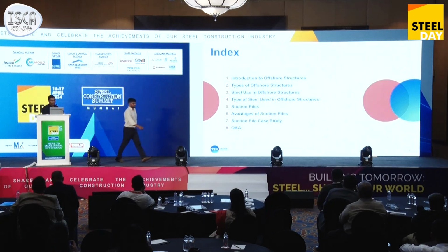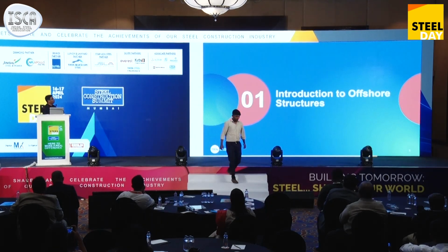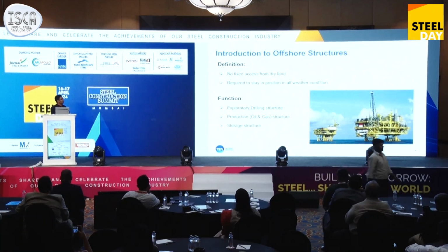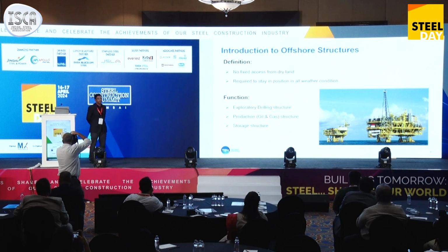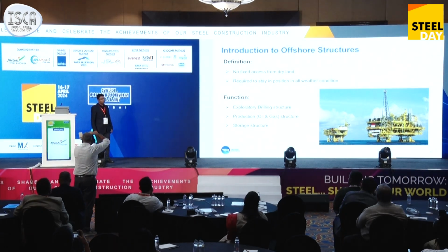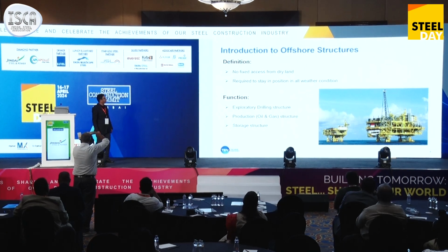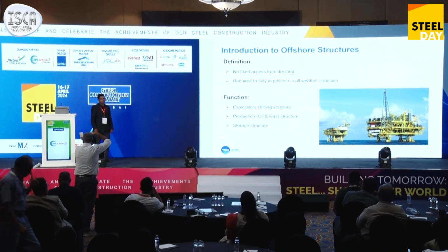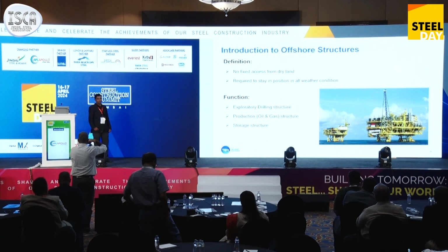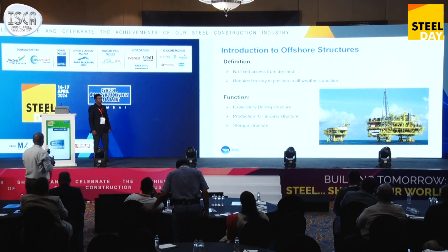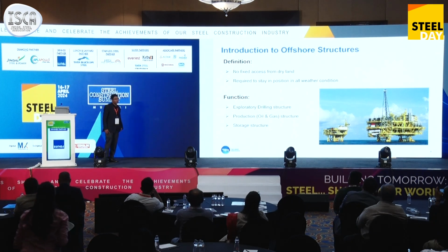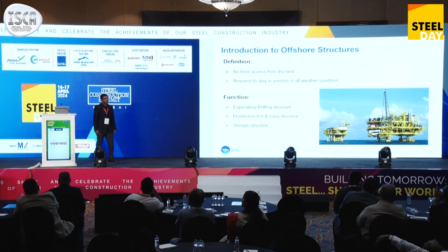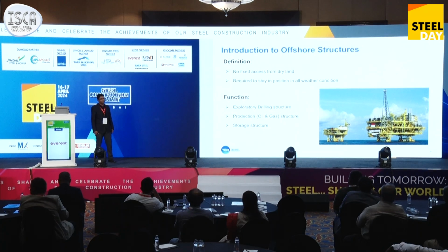Just to quickly brief you on what offshore structures are. They don't have access directly through land like onshore structures. We have to access them either by boat or by helicopter, and they are required to stay in position all the time, 24/7, for their design service life. An offshore platform can have a service life of 30 or 20 years, based on the capacity of the reservoir.